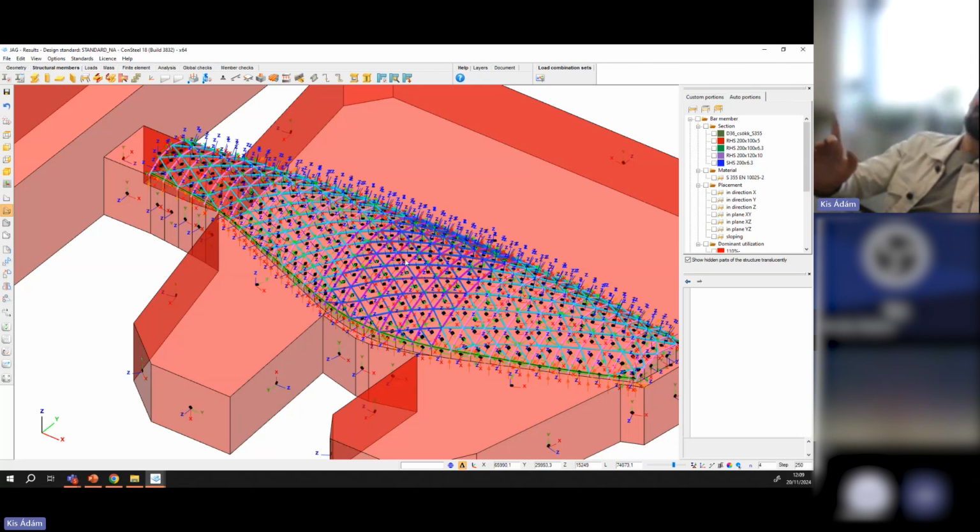So if the simulation surface local coordinate system is pointing outwards, it means that if we have a suction value, or a negative value, it will be a suction on the building. Because from the simulation results, we know only that we have a positive or negative value.